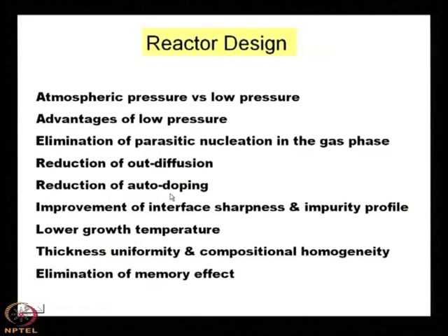When there is impurity diffusion from the substrate to the layers, it is auto doping. You are not doping through any chemical, it is automatic, from the diffusion of impurities which are there in your layers or in your substrate, or say if you have not cleaned this very effectively, because cleaning is also important.